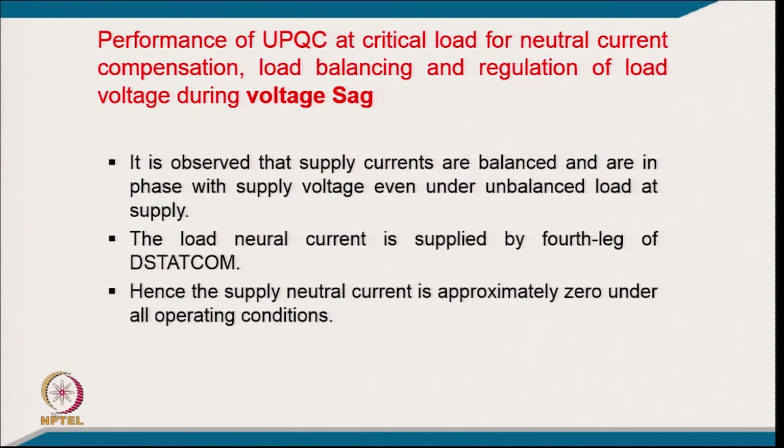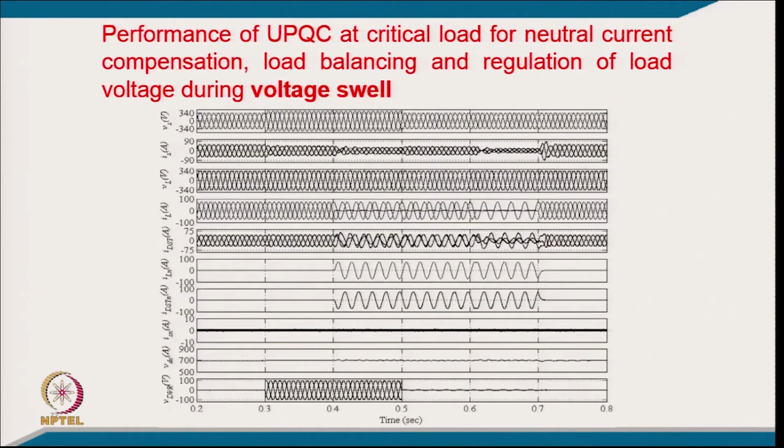So, these are applied again back. It is observed that the supply currents are balanced and in phase with the supply voltage even with unbalanced load, and the load neutral current is supplied by the fourth leg of the D-STATCOM, and the supply neutral current is approximately 0 in all operating conditions.